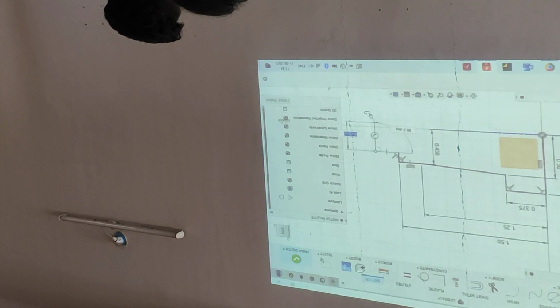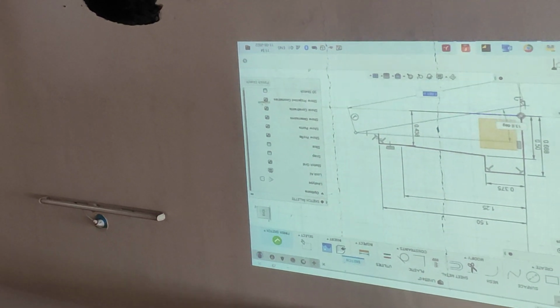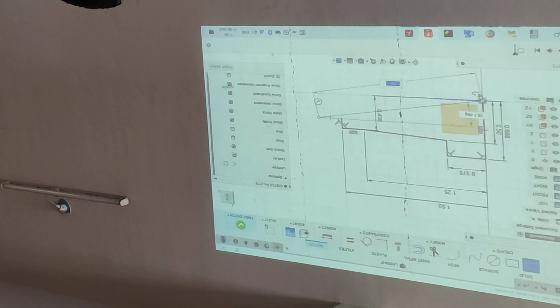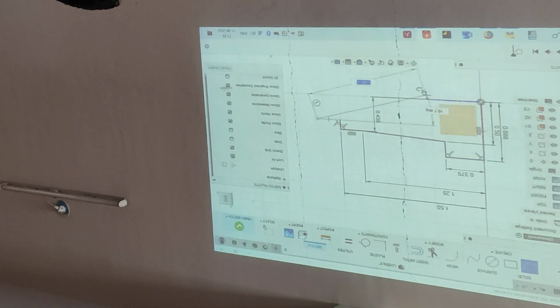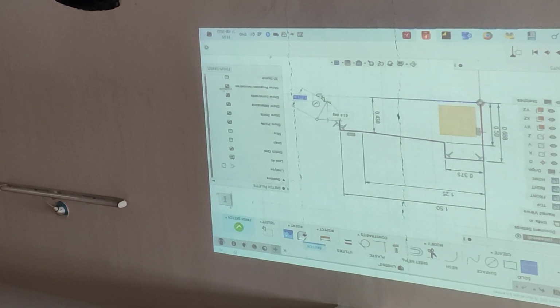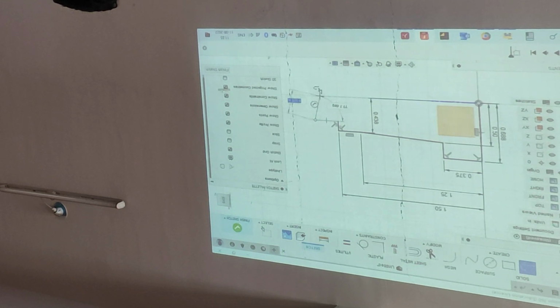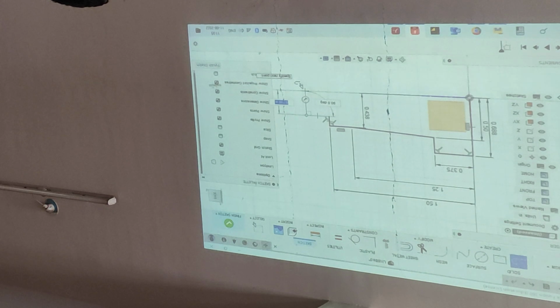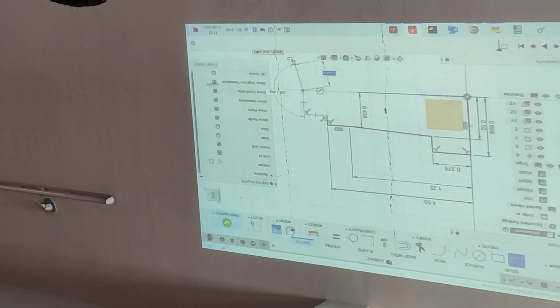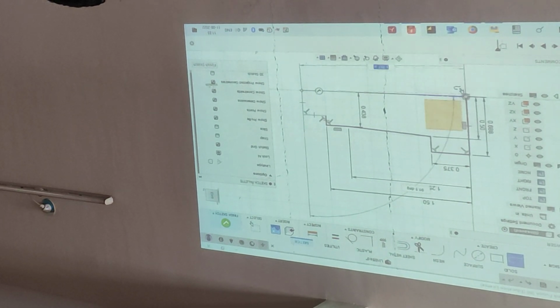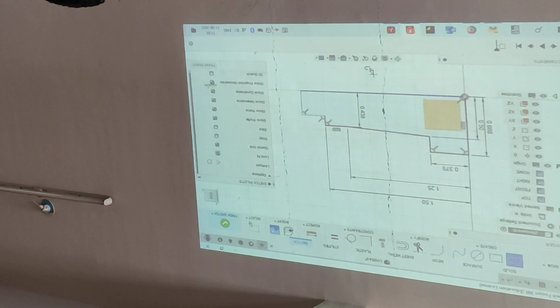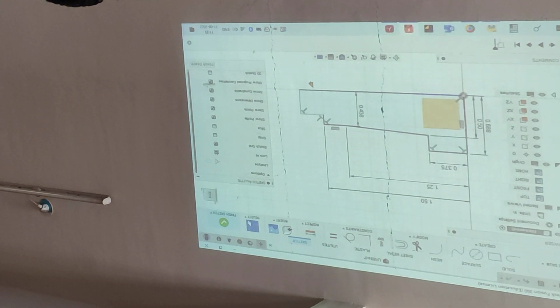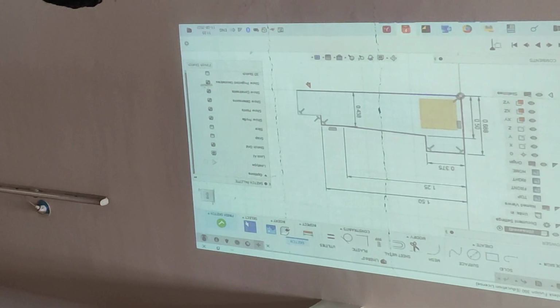And for closing, I can just go on top, click nothing, just go here, and when you come like this, it will give you a blue dotted line. Okay, that is called cursor tracking. So you are taking the reference of that point and clicking here, and then finally I will go back to the origin and close.